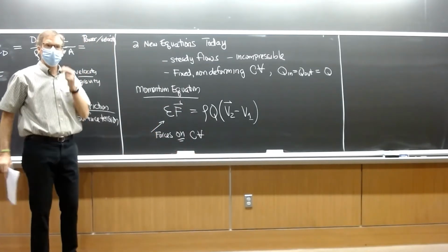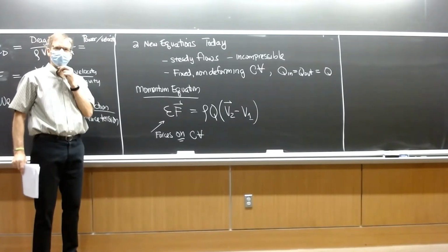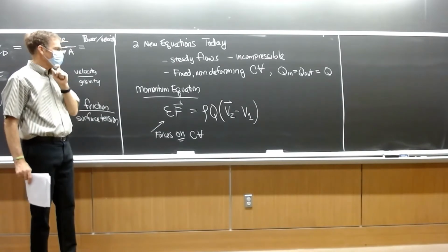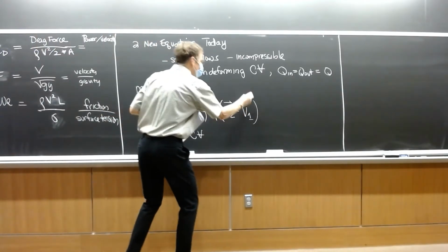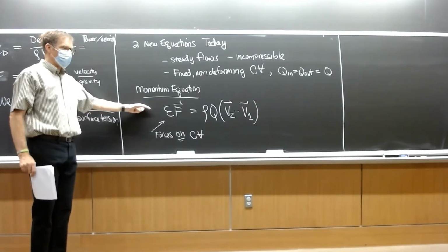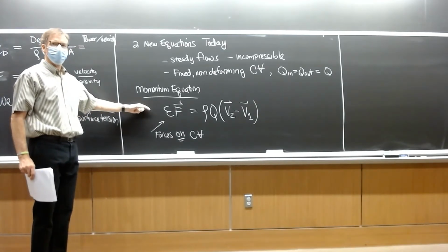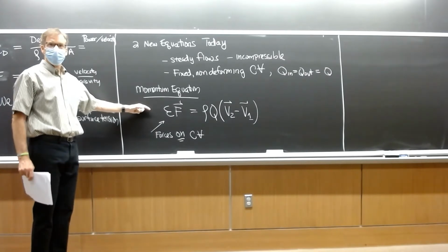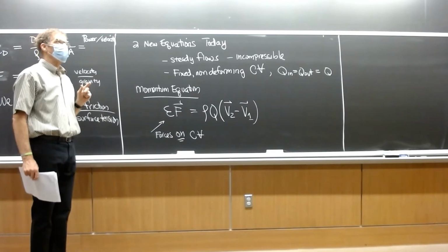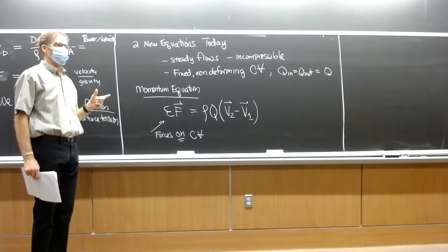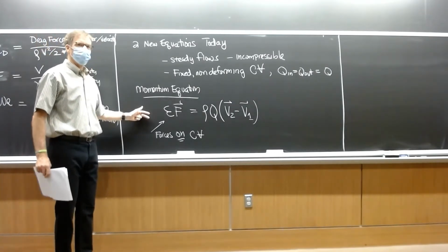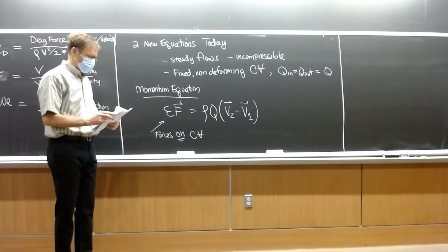This is the only problem that I know of where you can, yeah, Cordell. Is V2 a vector and V1 not a vector? No, I just haven't gotten it up yet. Gotcha. Yeah, thanks. This is the only equation, of the ones that we most commonly use, that is a vector equation. It's also the one where when you're asked to calculate a force on a control volume, this is the only equation available to you for that. So that's the first of the two equations.